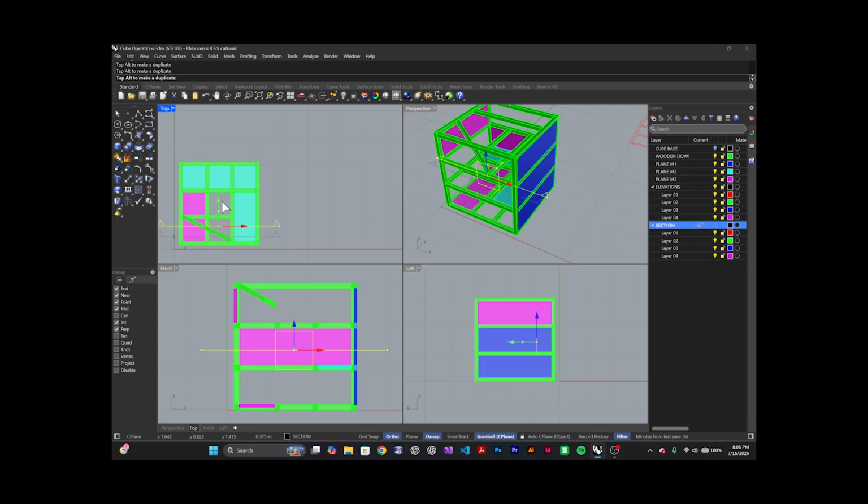And then if we move it back, we're going to see this guy moving. So this is what we want. But what happens right here? Why can I not see it here or on my top view? So we have to activate the clipping plane on those viewports as well.